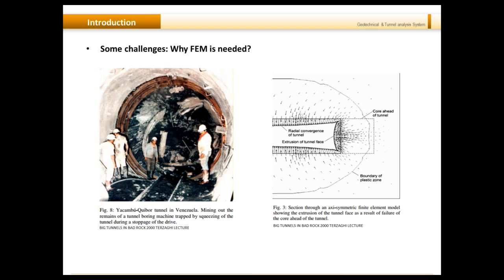So to simulate or understand how much face pressure would be occurring, you definitely need a finite element model. This is a section that is cut through a 3D model, and you can see here there exists a plastic zone around the excavation, and the soil or the rock strata tries to squeeze into any kind of opening that is there. Now, they are based on the constitutive material models and the soil properties.